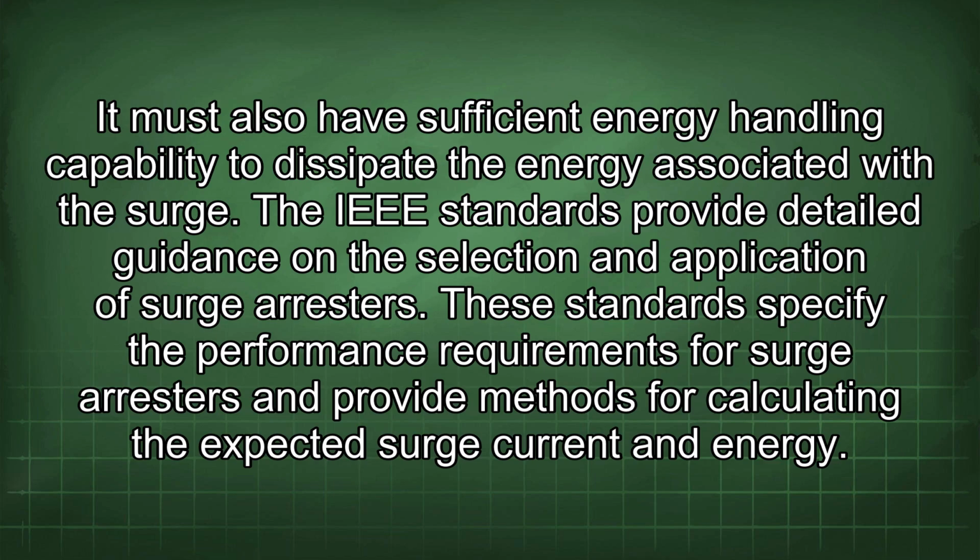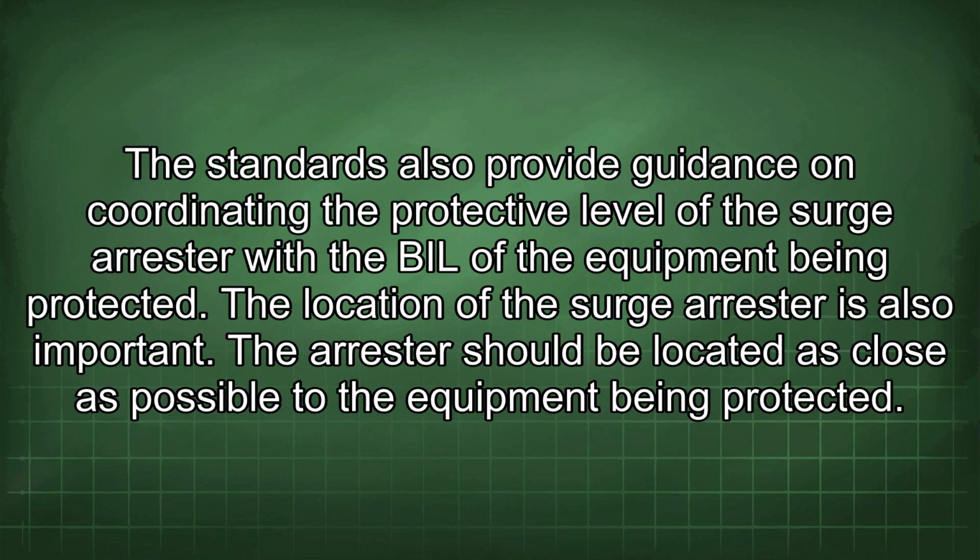The IEEE standards provide detailed guidance on the selection and application of surge arresters. These standards specify the performance requirements for surge arresters and provide methods for calculating the expected surge current and energy. The standards also provide guidance on coordinating the protective level of the surge arrester with the BIL of the equipment being protected. The location of the surge arrester is also important.